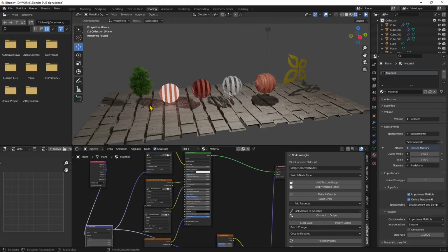And so sometimes some of these effects can be used to improve your scene, but displacement is a really heavy effect if we compare that to bump and normal. So bump and normal are like fake 3D effects to keep the scene not too heavy. Same goes for the alpha channel effect or opacity effect or cutout effect.